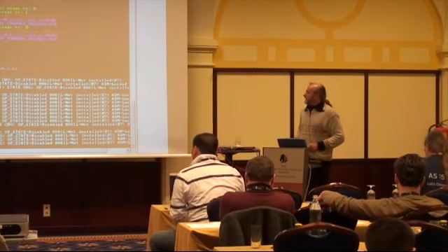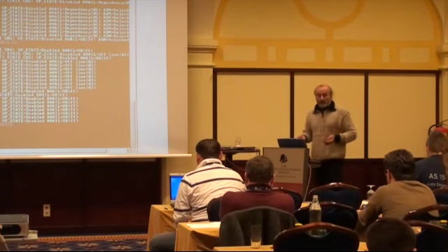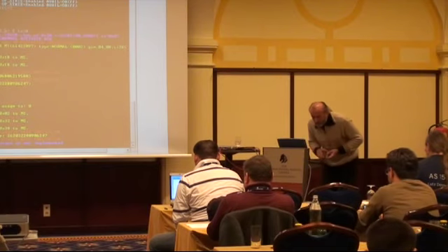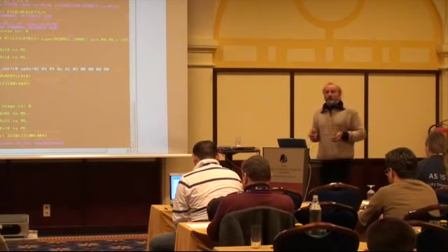So OpenBSC starting up again. Those messages are now the configuration messages when OpenBSC configures the BTS. Now this cell should be visible to the public. So if you do a manual network search with your phone, you should see 00101 or testnet. Has someone already registered? Okay. Testnet or 00101. It depends on the software on the phone, what name it displays for this special network.